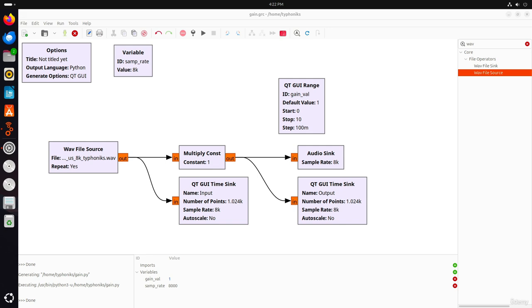In an ideal world, the output of a low-pass filter would look like this. Frequencies below the cutoff are unaffected and retain their original strength. Frequencies above the cutoff are completely removed as though they never existed. Let's consider a signal represented by an FFT, fast Fourier transform, showing frequency components from low to high.